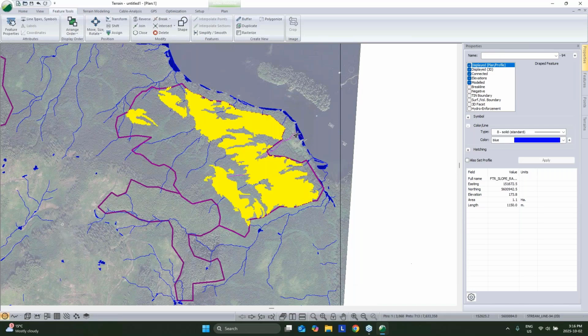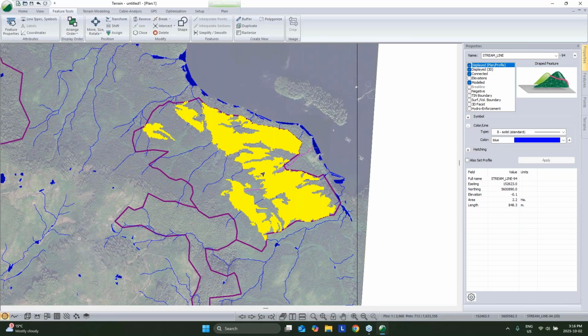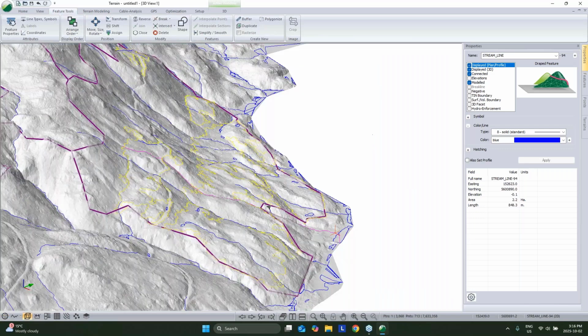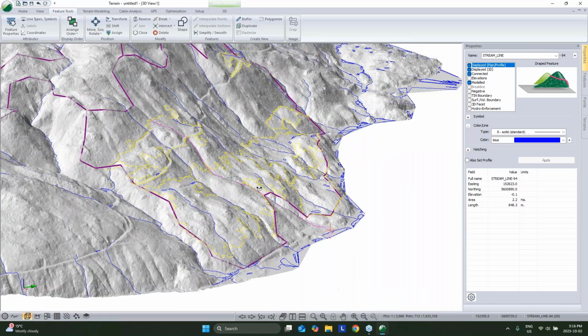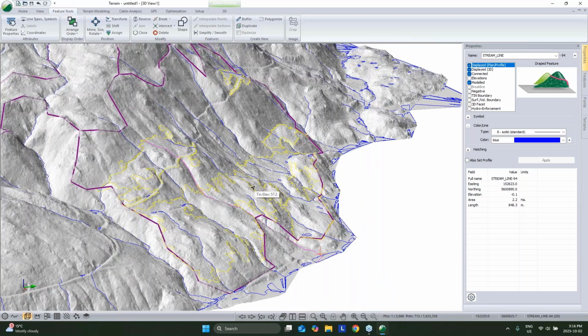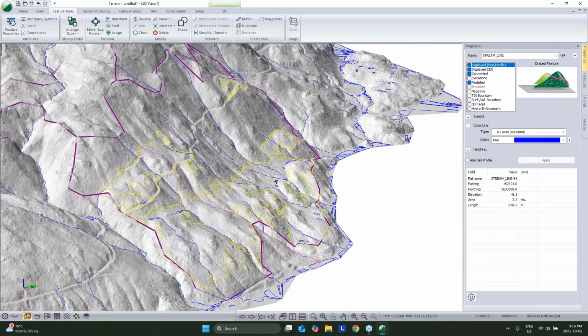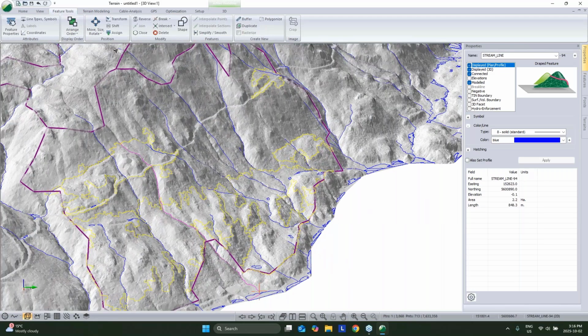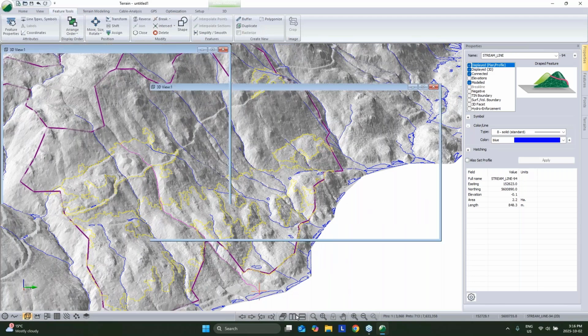And we can see, well, we've actually got an awful lot of that block that we could shovel log or hoe chuck if our road was down here, and looking at how that really looks on the 3D, yeah, it makes sense. So here, if I wanted to see, well, if I had a road down here, where would it make sense to put my landings? I could use that same tool.